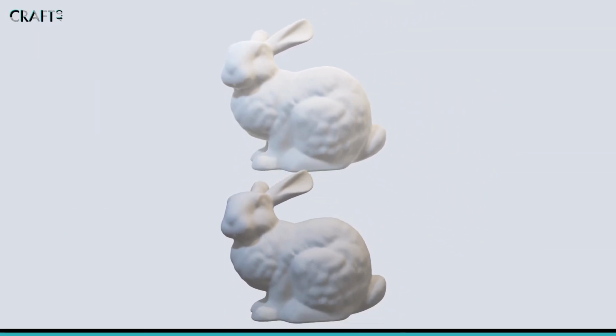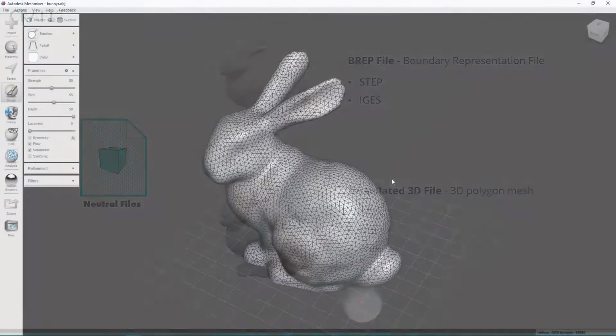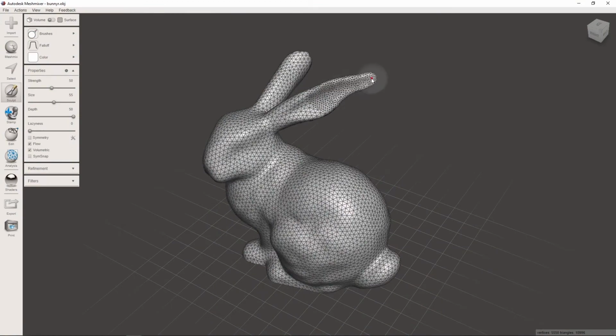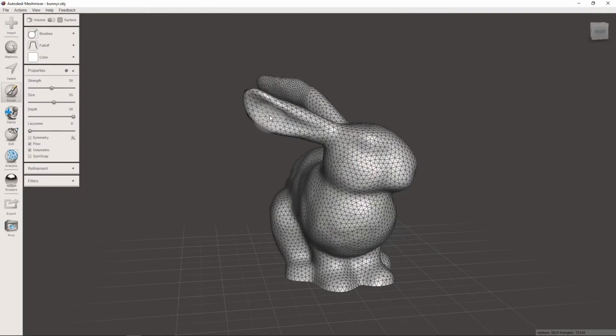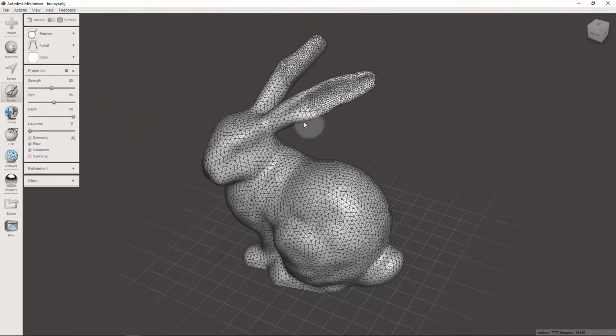More recently, the industry has developed the 3MF file, which can contain more information specific to 3D printing, as well as checks and balances to reduce the errors of use in these files. These tessellated models have even more limits in their reuse or modification. Traditional CAD packages struggle to modify these geometric types, and if modification is required, specialist tools and digital sculpting approaches are most commonly used.